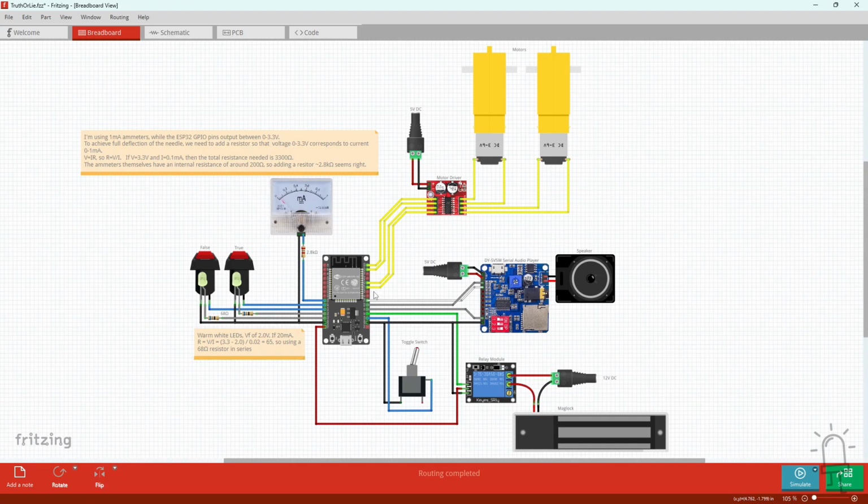Now you can send commands in your code to trigger playback of specific audio files saved on the SD card. But in addition to the transmit and receive serial lines, I've also connected the busy pin, which is this grey pin at the bottom here, and that's going to go high when an audio file has stopped playing. And that's how the code on the ESP32 will then know to prompt the user for an input.